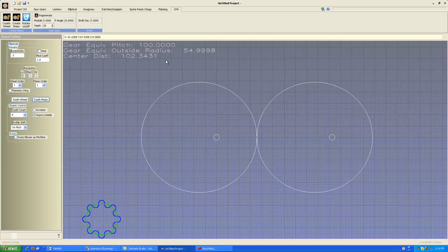You'll remember on the original elliptical screens, you had to use an odd number of teeth, because if you used an even number of teeth, this would happen, where you'll notice on an even number of teeth, we have a hole at both 90-degree extremes of the gear, which means that if we had the identical gear over here, we'd have a hole on each side and we wouldn't be able to mesh.